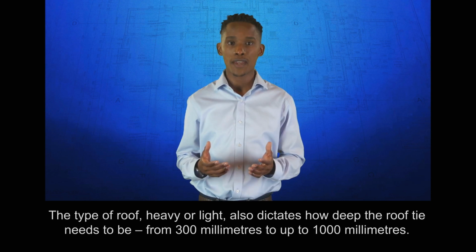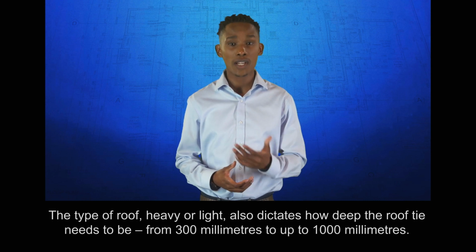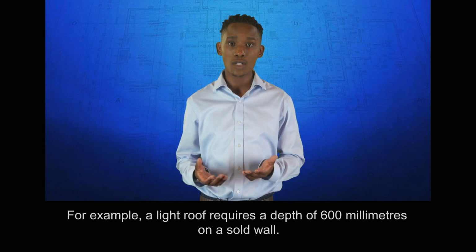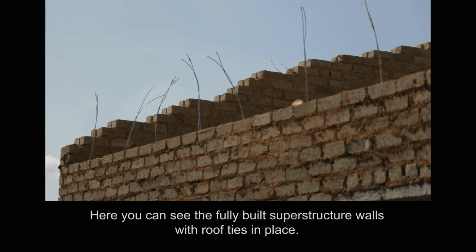The type of roof, heavy or light, also dictates how deep the roof tie needs to be, from 300 mm up to 1000 mm. For example, a light roof requires a depth of 600 mm on a solid wall. Here you can see the fully built superstructure walls with roof ties in place.